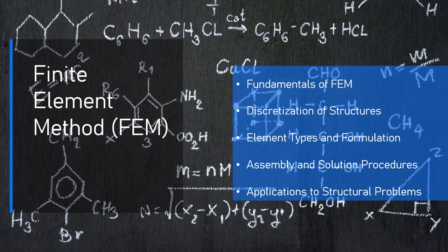3. Defining material properties. Each element is assigned material properties that characterize its behavior under load. Elastic modulus, E, describes the stiffness of the material. Poisson's ratio describes the material's response to axial deformation. Density. For dynamic problems, the material density may be used to calculate the mass matrix. Thermal properties. For thermal analyses, the material properties like conductivity, heat capacity, and thermal expansion may be needed.